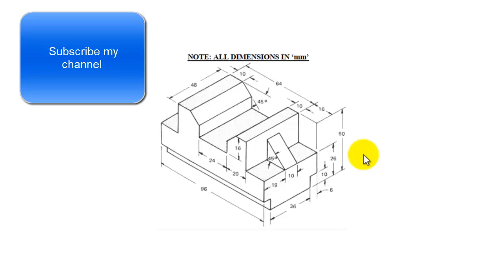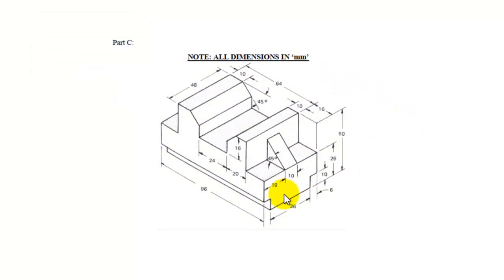In this video tutorial, I am going to design this model. The units are given in millimeter, and I am going to start my sketching from the right plane. I am going to design this sketch and then pad it to 96 millimeter, and then I am going to design these two hubs and then this rib. So let's start it.